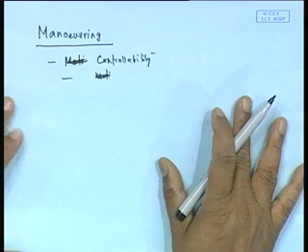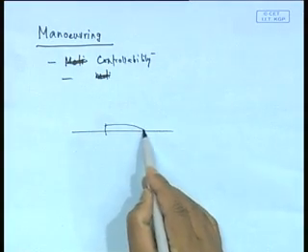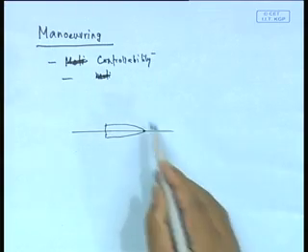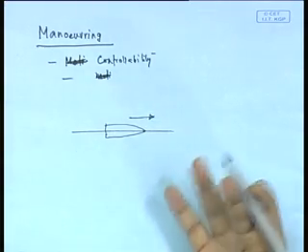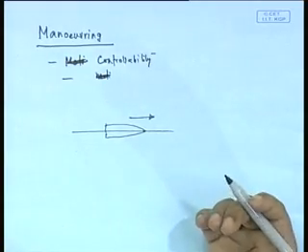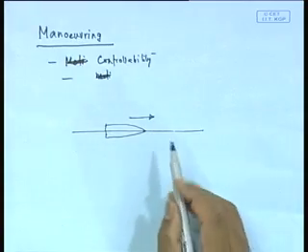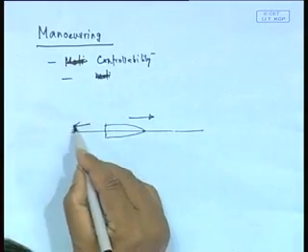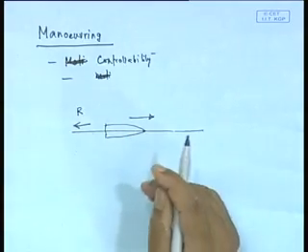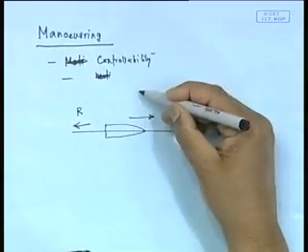Assume this piece of paper is the sea surface, calm sea surface. I have the ship here going along a straight line. This we studied, this is the standard wave resistance problem. That is, when the ship is moving along the forward line, the net force that comes from the hull is in this direction, which is my resistance.